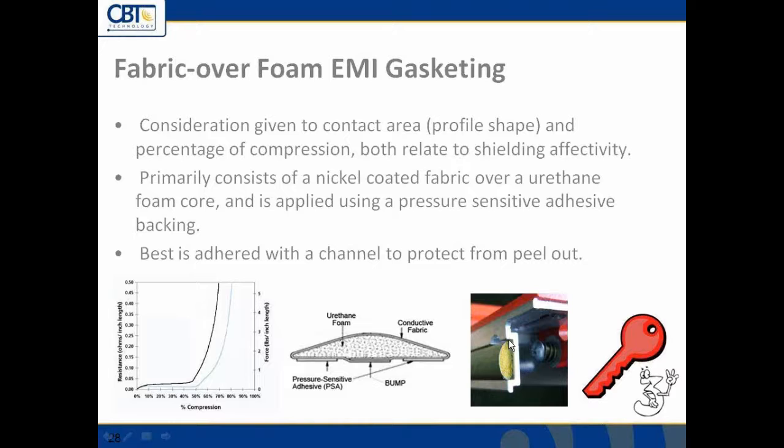That's why we recommend extrusions in a case like this. And then obviously making sure that you're maintaining that gap that we talked about earlier between each one of those front panels, to make sure that you have the right amount of compression without being overly compressed so that it becomes difficult to insert and extract, but of course not being under compressed so you lose EMI effectivity as well. So, things to keep in mind for that.